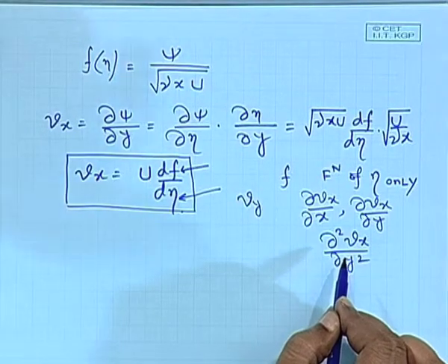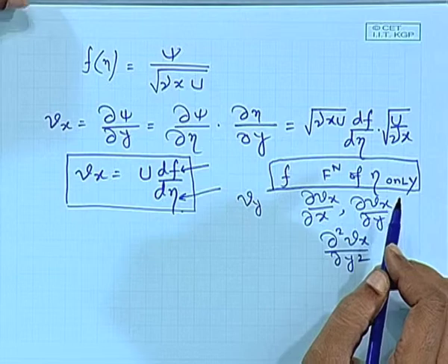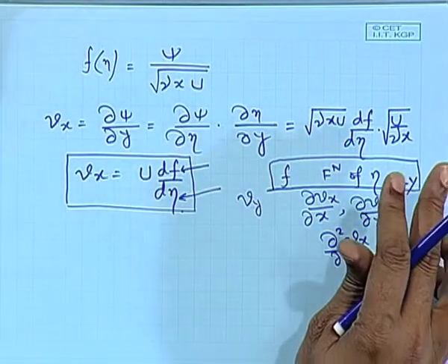Substitute them back into the governing equation. And if your similarity parameter is chosen correctly, all the x and y's from all sides will cancel out. What you will be left with is f and eta. So, basically if you have only f and eta, it is no longer a PDE, it has to be an ODE, since by definition f is a function of eta only. That is the essence of similarity parameter or combination of variables.